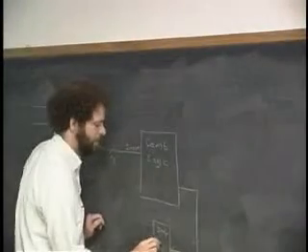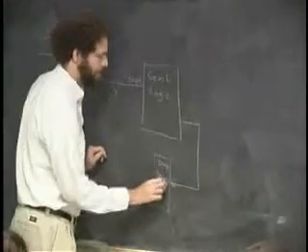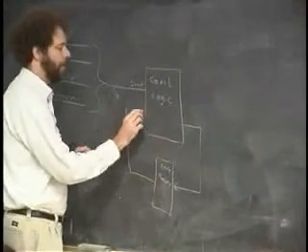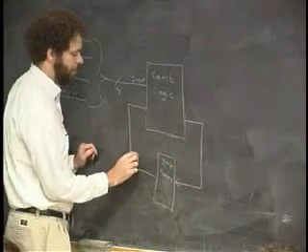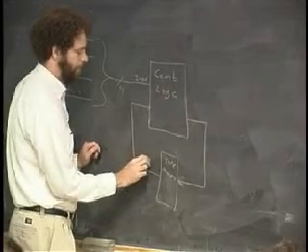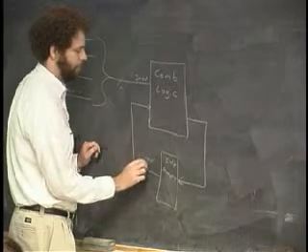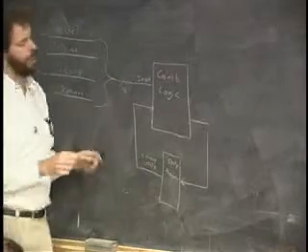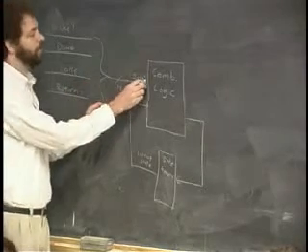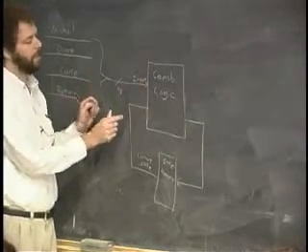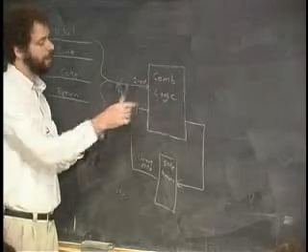And that state memory will put out, and I don't know how many bits it's going to take yet, what we're going to call the current state. And the machine's job is to remember the current state, consider the input, and on the basis of those 2 pieces of data, the logic table will tell us, if I'm in this state and the input is such and such, what should the next state be?